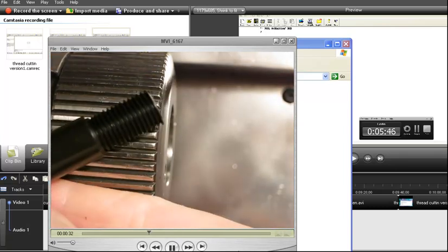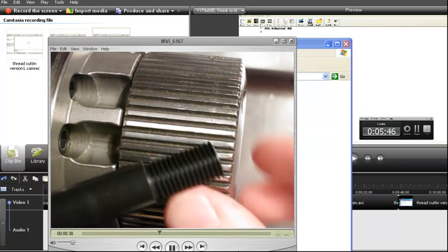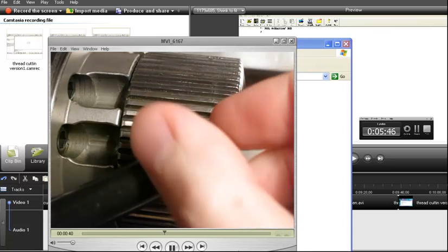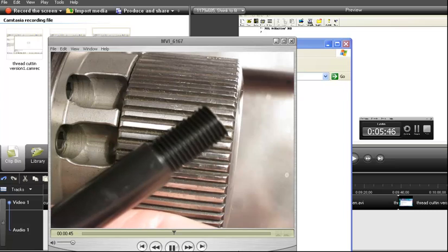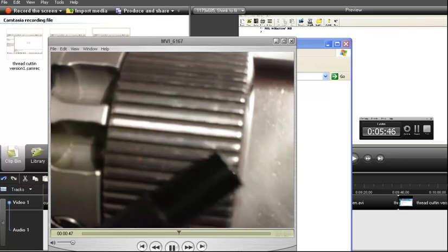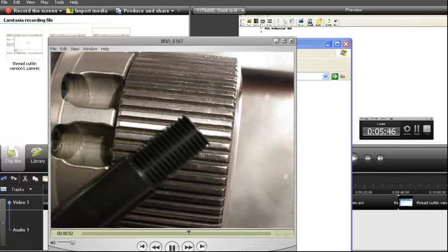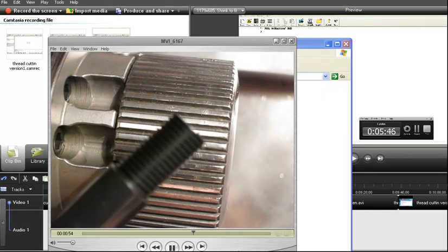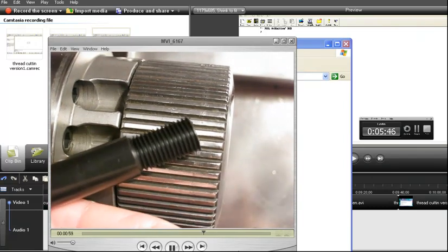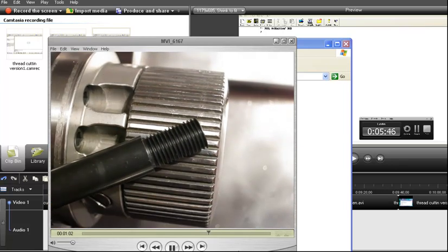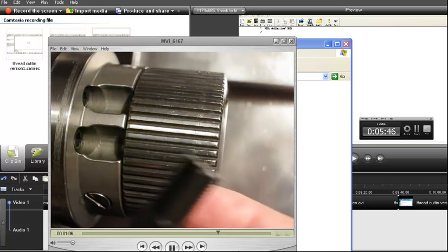Not everything, the tool change operations start, the tool changer starts to rotate crazy, and goes to the part where I need to cut threads. The machine stops, and I get a message about the encoder. Check your encoder.